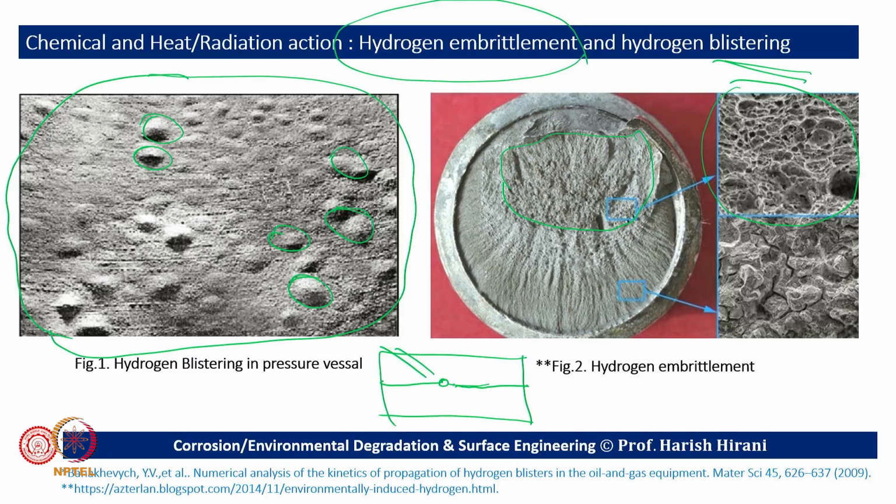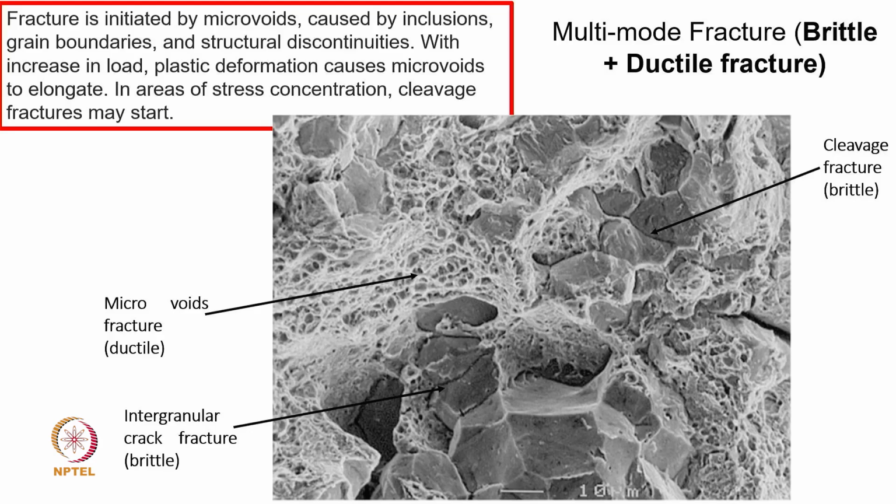This is possible, and it happens in a number of materials including titanium and steel. We need to think carefully about what has happened and why the materials are failing, particularly because of hydrogen embrittlement, and it happens more commonly in marine environments. We need to think from that angle also.